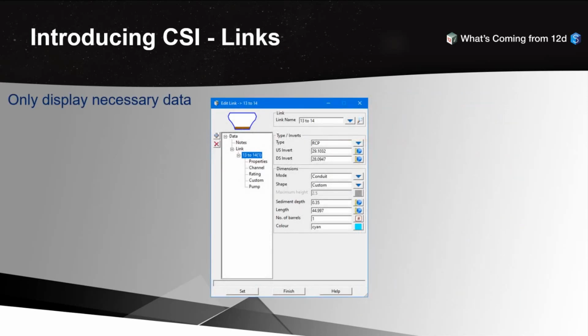Moving on to links. Again, we were trying to keep the link panel as simple as we possibly could. We've got a few new things here. So the link shape is now displayed on the main panel, and as you can see, there's a brown stain in the bottom of that one. So that is the sediment depth in that particular link. Previously, if you had sediment depth, it wasn't intuitively obvious. You had to actually be looking at the widget for the sediment depth to know that you had sediment depth applied. What we've tried to do here is give you a visual indicator that you've got sediment depth applied to that conduit.